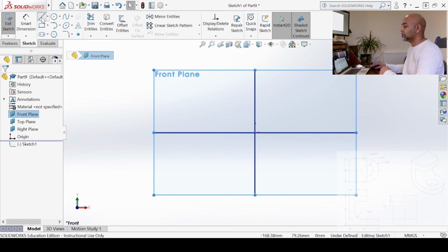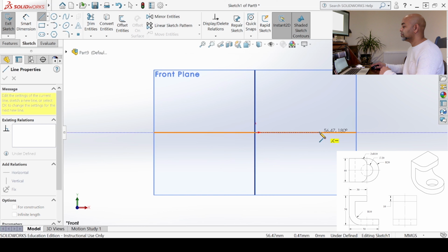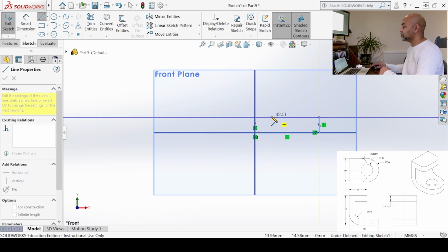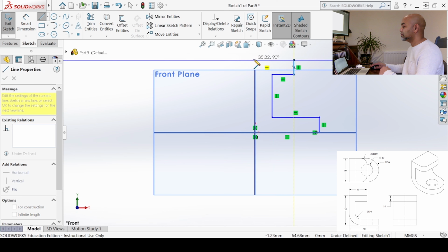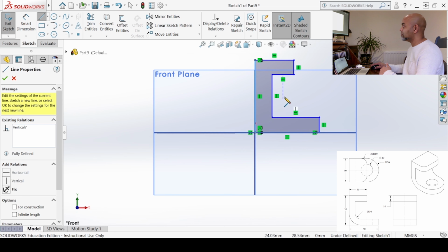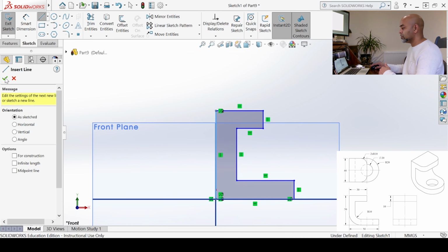Okay, using the humble line command, I'm going to snap onto the origin, click across, up, across a little bit, not committing to any snaps if I don't intend to. So I've created that rough profile, which is an edge shape, really. It's not accurate yet.